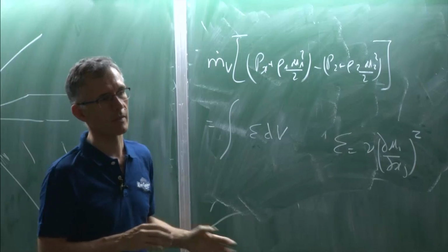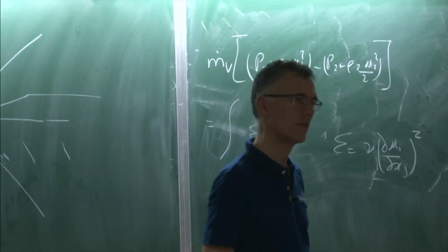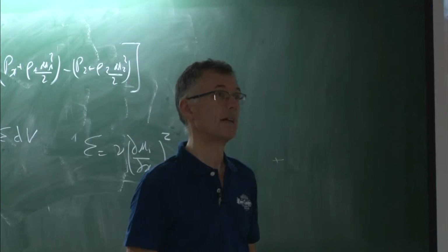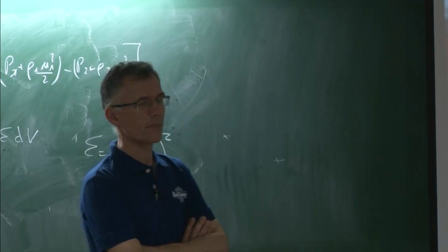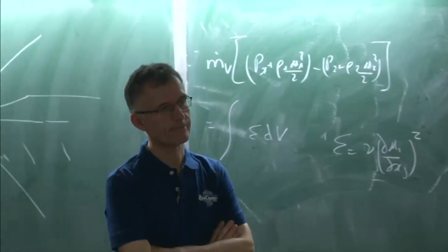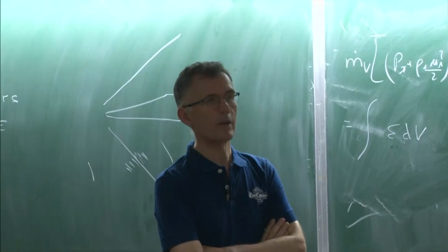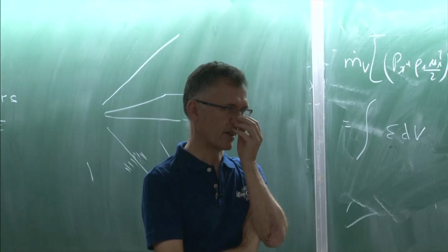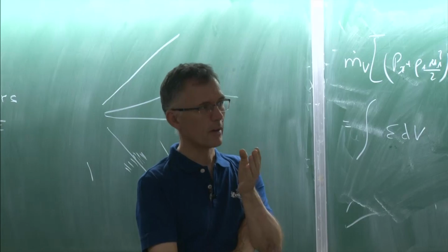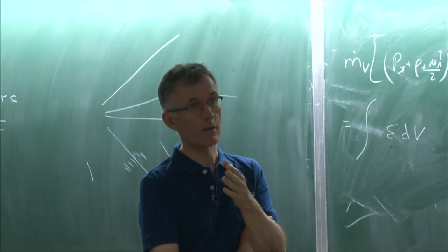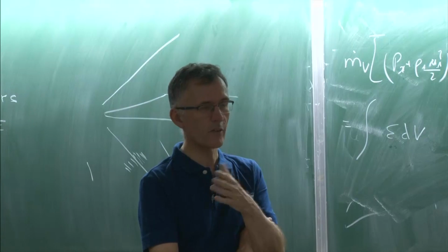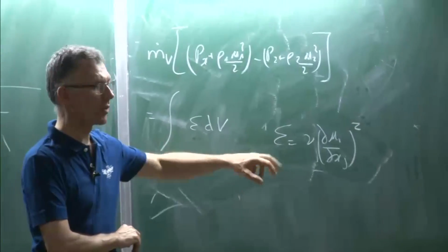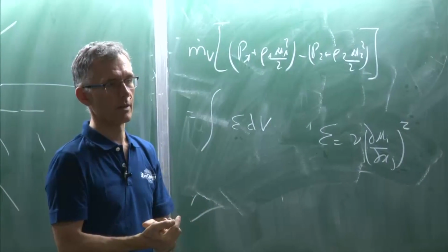Is there any specific reason as to why it's not just velocity and pressure? Would species also matter, or do you think some meshing has to be done based on species variance? Well, for the moment, I didn't talk about species, okay? There's no combustion here, no mixing, no nothing. It's only flow. And for the flow, what it's telling you is that pressure or velocity or vorticity, none of this is as important as this quantity. This quantity is what creates the pressure losses.